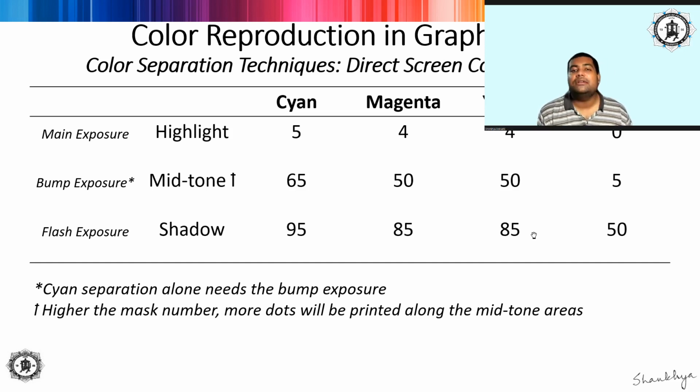Calibration of the darkroom conditions to your film and processing conditions can be rather lengthy, and it's a trial and error method. However, once calibrated, the procedure becomes much more scientific, and it becomes less of a trial and error method. But accurate control of all exposure is a must if good production quotas are expected. Variation in succeeding transparencies and masks will have to be compensated for, to eliminate expensive redoing or reshots.